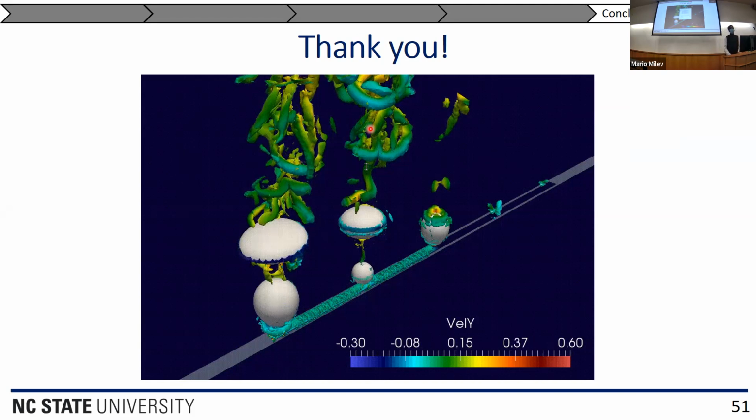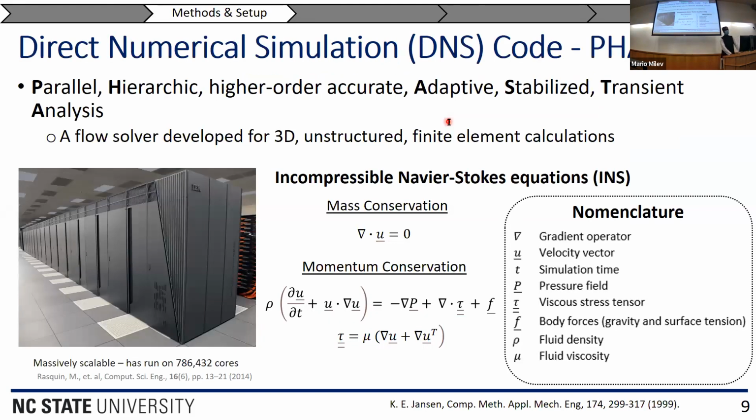And there's a question over there. Can you go to page 9? There you go. What is the last equation? This one? Yeah. This is the viscous stress tensor. This is essentially what we use to look at how the velocity, the viscosity, diffuses. It's the diffusion term in the Navier-Stokes equations. And so this tells us it's a Newtonian fluid. Typically it sits inside the equation, and sometimes it's not even separate. It's just looking at where the viscous stresses are.